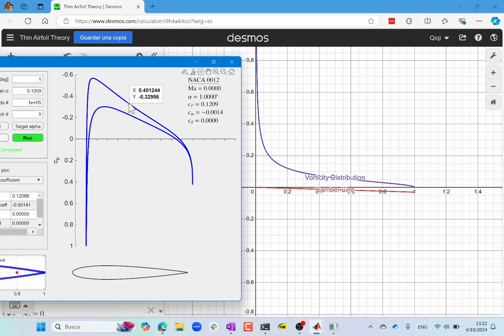That corresponds to the problem with thin airfoil theory, right? Thin airfoil theory assumes the effect of the vortices is small compared to the free stream, which is of course not true at the leading edge because the combination of the vortices has to cancel exactly the free stream at the leading edge. So it's not small, which means the difference in the pressure is not going to go to infinity at the leading edge. All right.